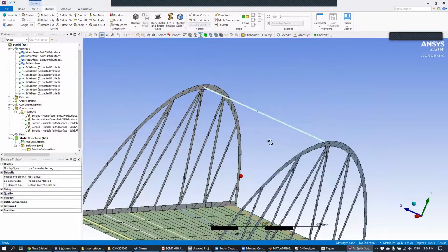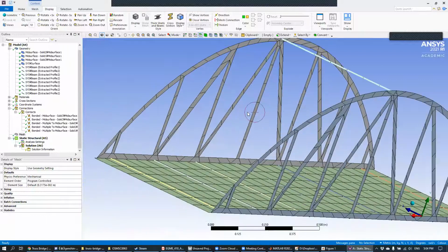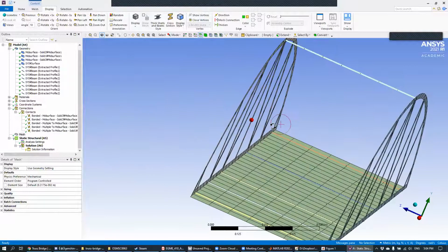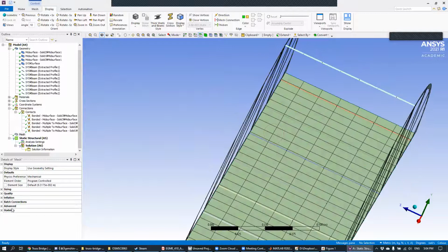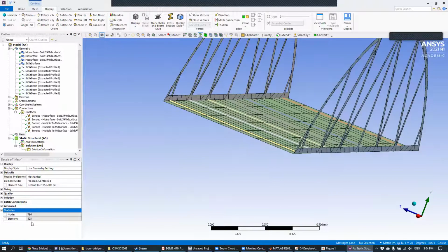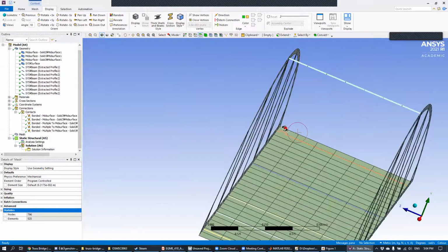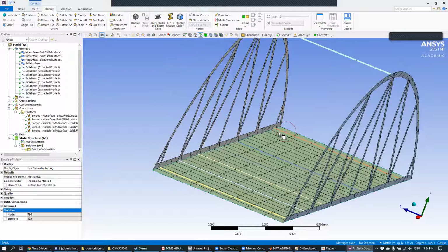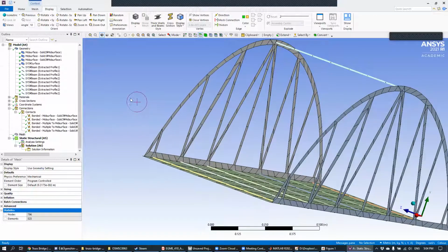And so this is cool. Now we've taken this 3D object and meshed it with a bunch of 2D and 1D objects. If you look at the statistics of this mesh, you can see this mesh is extremely lightweight. The number of elements is not even 550. I've only gotten an element count of 525. That's huge. That tells us that this mesh is really lightweight, and we can actually refine this mesh quite a bit.